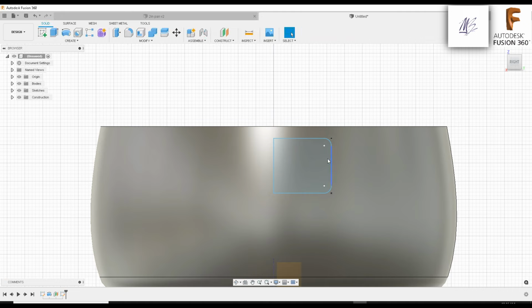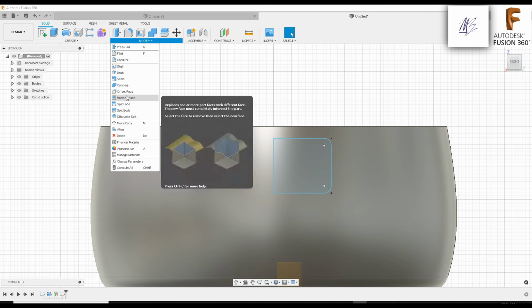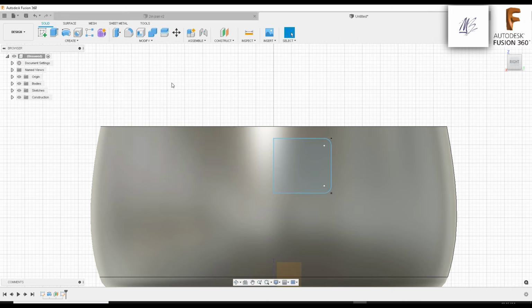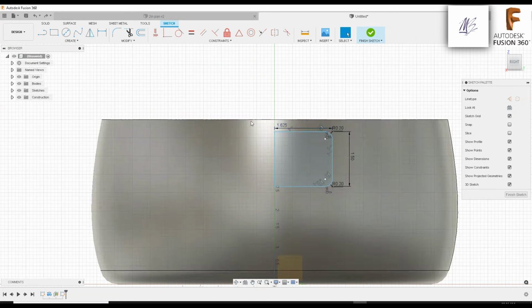Let's left click it. We want to extrude this profile, but before we do that, let's mirror it first. So we're actually going to go to modify. Oh, we have to mirror the sketch. So if you do Control Z on your keyboard, it'll let us back into the sketch function. You have to mirror the sketch before we finish the sketch.